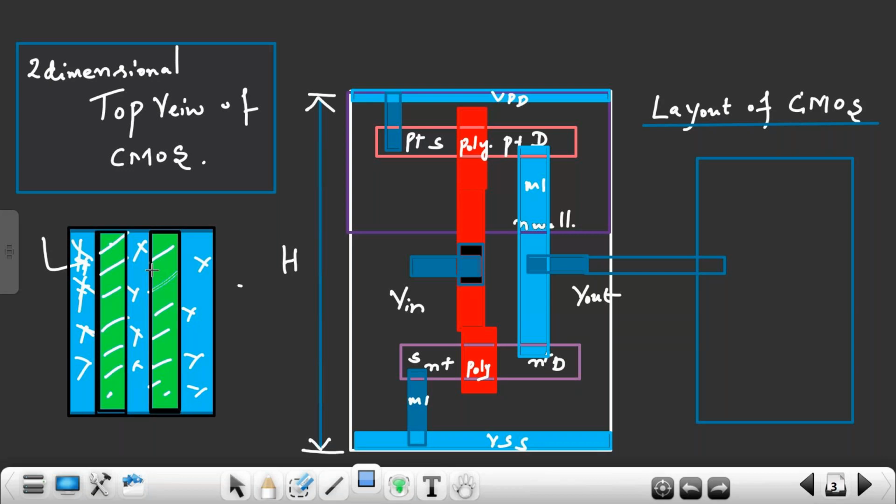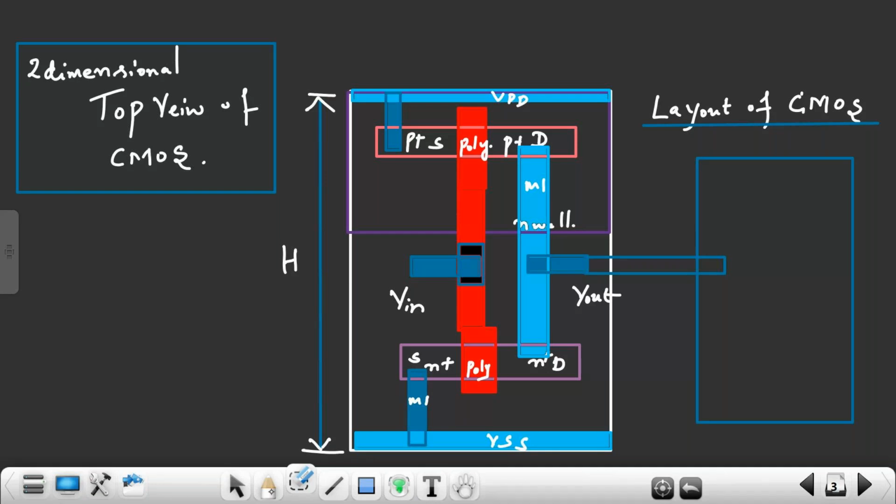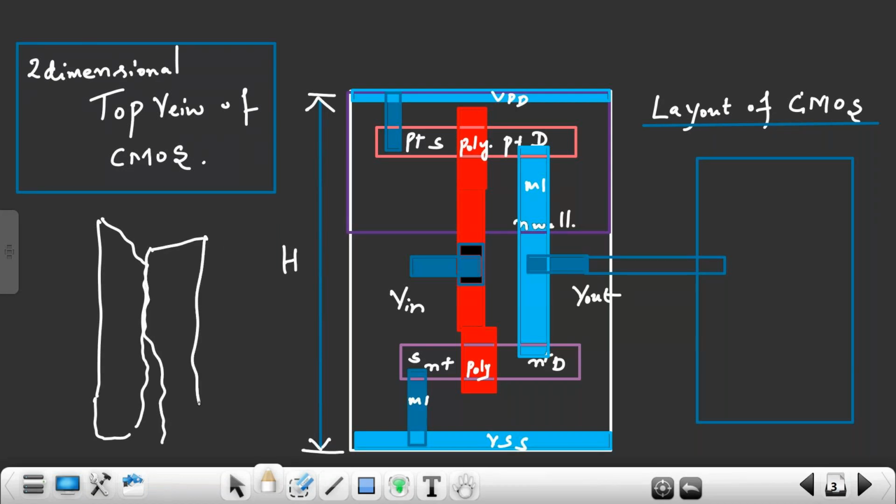So now why I am telling this is, it is a chemically driven process. So what happens is, when a metal layer is fabricated, it may not be fabricated in a planar structure. It may be fabricated like this. I'm talking in nanoscale. Nanoscale means 10 to the power of minus 9. In a scale, whatever you see is 10 to the power of minus 3, the lowest division of your scale. So nanoscale means 10 to the power of minus 9, and my metal layer can be fabricated like this. Here the acid has not worked properly, so both the metal layers are shorted.